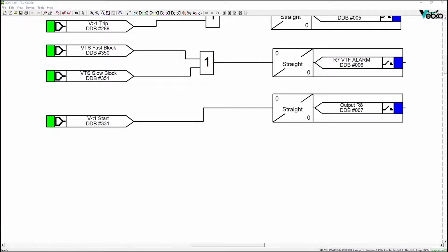Alternatively, you can assign a contact to the relay pickup. In this case, you can select the use binary trigger condition as specified below option in trigger. For example, record the pickup time by connecting the output of the relay contact to the default binary input C1.